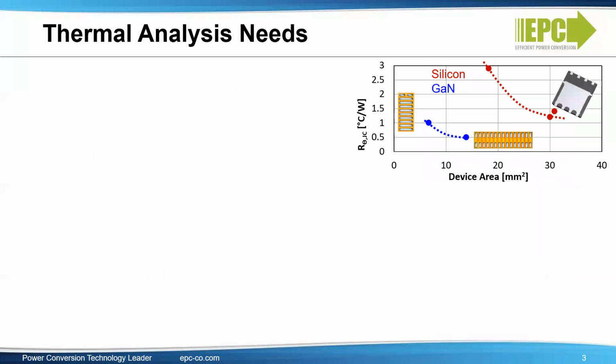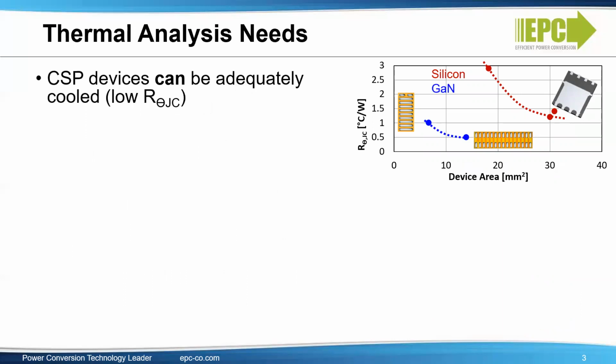So thermal management and design may cause some electronic designers to remain hesitant and cautious in transitioning from silicon to GaN, mainly due to some misconceptions relating to the device scale and the complexity of the thermal design. EPC devices benefit from a smaller device size, both electrically and by saving board space, but that does not have to come at the expense of thermals.